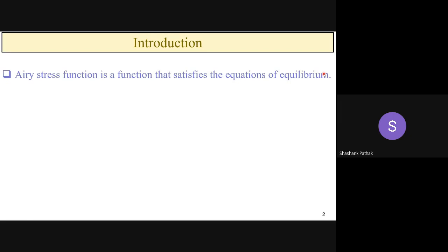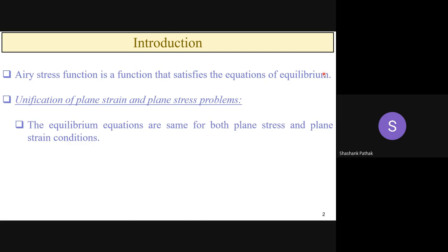Okay, so now, unification of plane strain and plane stress problem. If you remember, in the last class I also discussed that both the plane strain problem and the plane stress problem are connected by the equilibrium equations, because equilibrium equations are the same for both plane stress and plane strain conditions. So it means there can be some connecting link between these two types of problems.